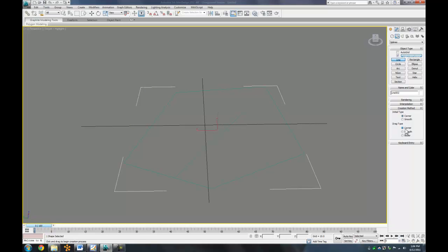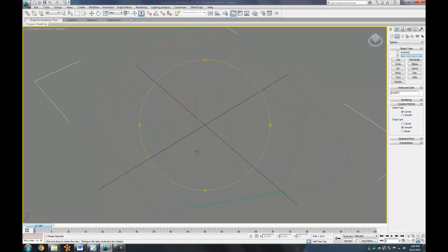On the right side, we can change the creation mode to smooth. What that does is, click once, I click and hold the second time. Now I'm able to drag a smoother corner. Third time at that side, fourth time here, and I'm going to close my spline again. This can get a little bit tricky.